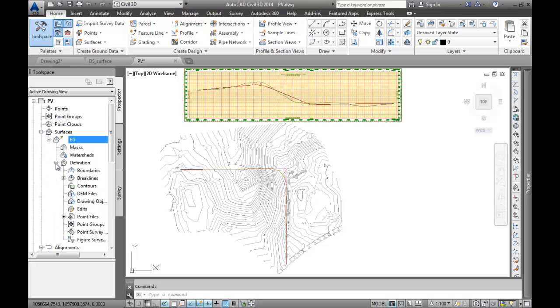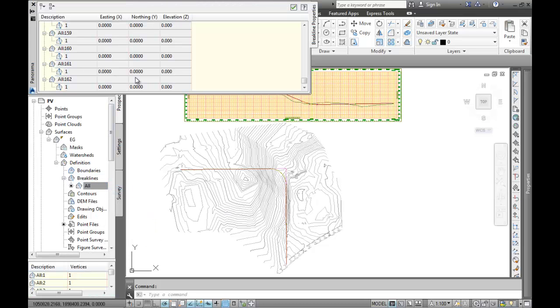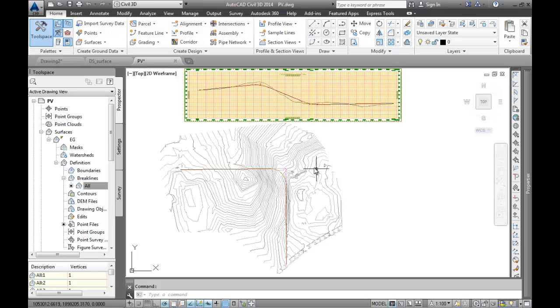And what came over from the surface? Well, we have the point file. This is an indirect reference. We're actually referring to a file source, so that came over fine. We have a bunch of break lines. What are their properties? The break lines disappear because they were referring to figures that referred to a database over in the other drawing. So we really don't get, with a classic Wblock, exactly what we expect over in our profile view drawing. Also, we end up with stuff that we probably don't want in here.